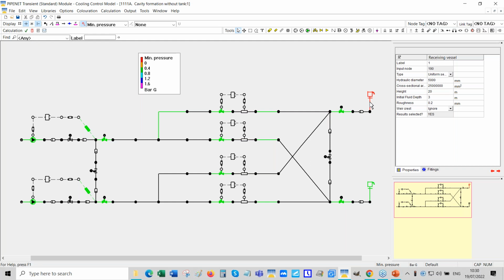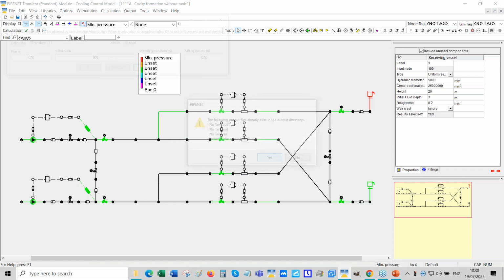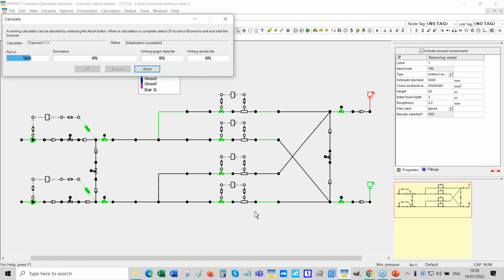You see, we're increasing the height from 5 meters to 20 meters. So we're increasing the elevation back pressure by 15 meters, which is approximately 1.5 bar increase. That's the reasoning behind increasing it to 20. That's quantified by the level of the pressure that we were getting here.